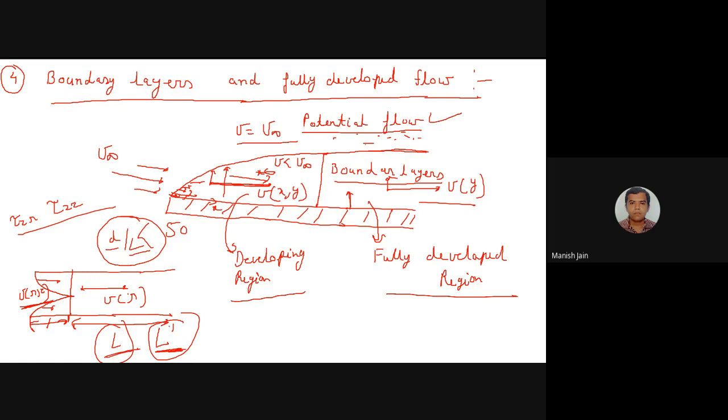So when you use the effective length, that will take care of the difference coming due to the developing region. Okay, because the equation we will use is for the fully developed region only. But because the actual pipeline condition has the developing region also, we will change the length of the pipe. That type of adjustment we can do whenever you solve a problem in a real scenario, so that your answer will be correct and it will not take a lot of effort.